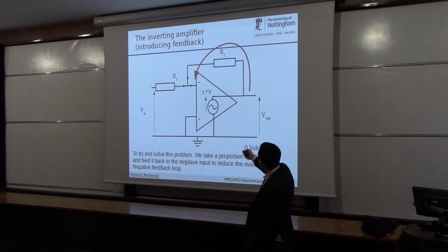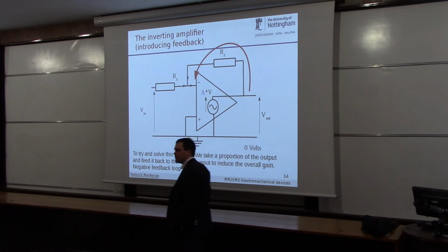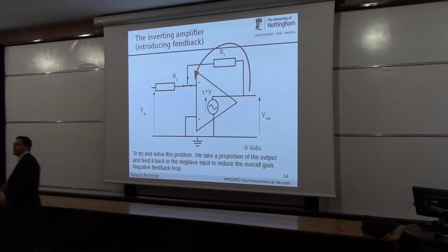Can you see we've got two resistors in series here? What does this remind you of? Two resistors in series. Arthur's been teaching about these. If they're between a supply voltage and 0, what would you call it? Something beginning with P and the second word D? Potential divider. Yeah, so potential divider. So what this is doing is basically sending some current back and dividing the voltage. You can think of it a bit like that.